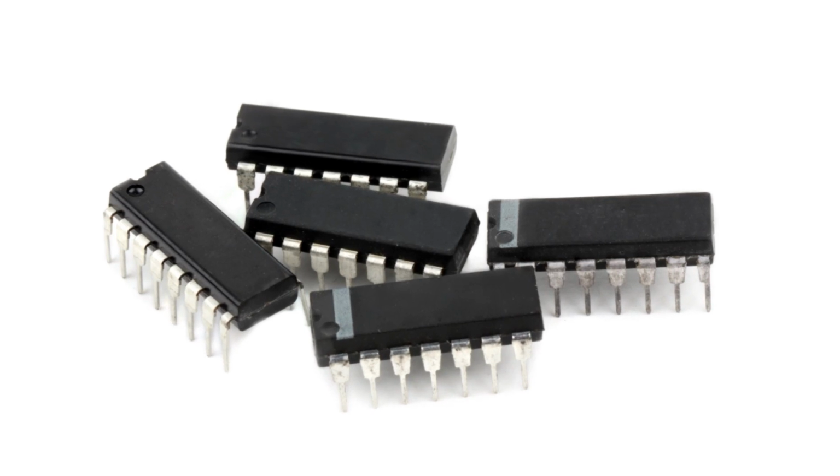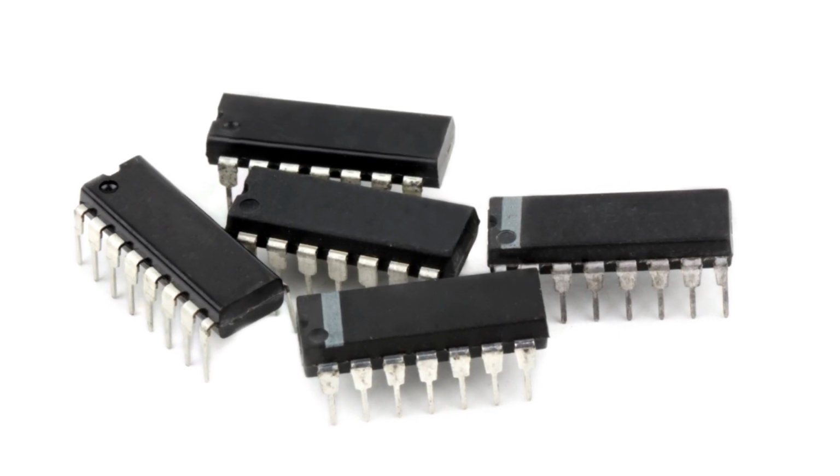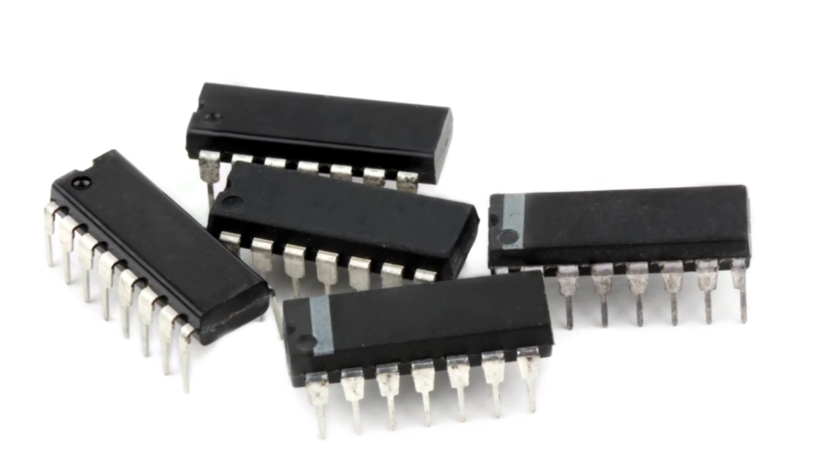If we add enough voltage to this side of the transistor, that is enough to attract the electrons to itself. Some electrons will recombine with the holes at the top, and some electrons will move to the top. In this way, we've generated another depletion region. With this structure, electrons will move through the transistor to the battery and back into the transistor. MOSFETs are interconnected to form logic gates, and the logic gates are combined to form the processing units that perform logical and arithmetical operations.